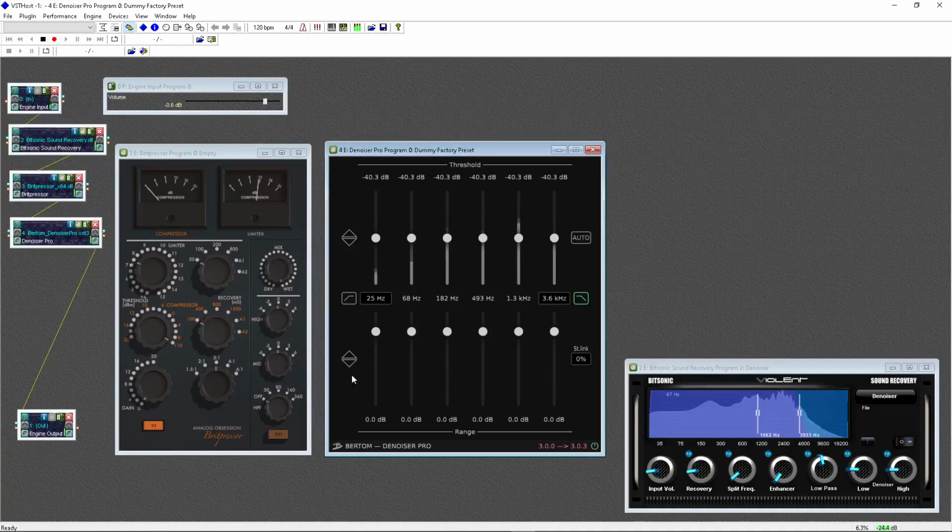Okay. Next thing I want to do, let's bring these down. I'll run these down about here. So 3.6. I set this up around about 125, 140 hertz, and I'll show you why. Because this is very handy. If the copy is marginal, right? Let's put it at 150 hertz. If the copy is marginal and these guys are running a lot of bottom end, all you're going to hear is bottom end. So what you can do is you can hit this button right here, and it will roll off everything below 150 hertz, and it will be much easier to copy. If a guy's just in the noise floor and he's running a lot of bottom end, that's a problem. Right, so this is a feature right here.